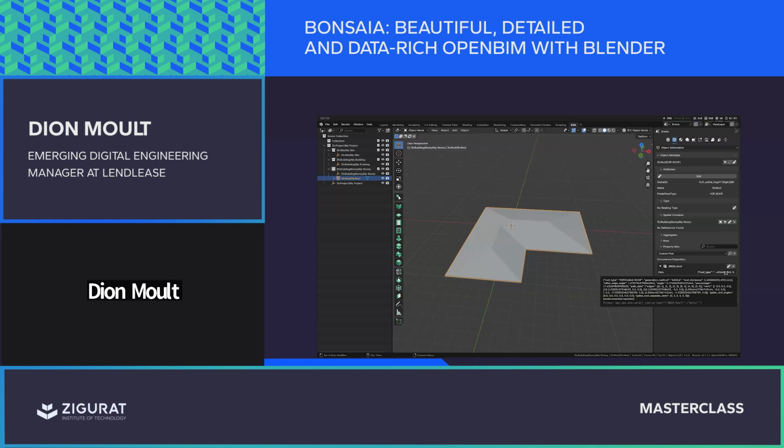And it's no different with geometry nodes. We will simply have to come up with a convention for geometry nodes. This is not something IFC will go and dictate. It will merely give you a way to reference an external system or external material shader or just some sort of external thing. And then we will have to come up with a convention that says, okay, for geometry nodes, this is the way that we reference it in a standardized way, store it in external files and so on, so that it can be linked. So that's the strategy of how you do it. So it can be done, but as an externally referenced system to IFC.